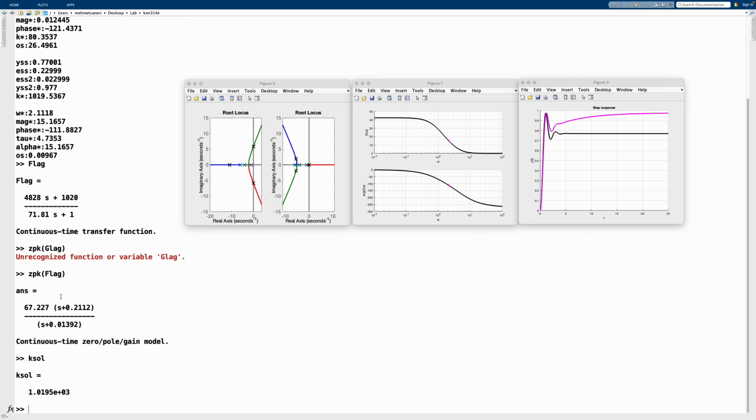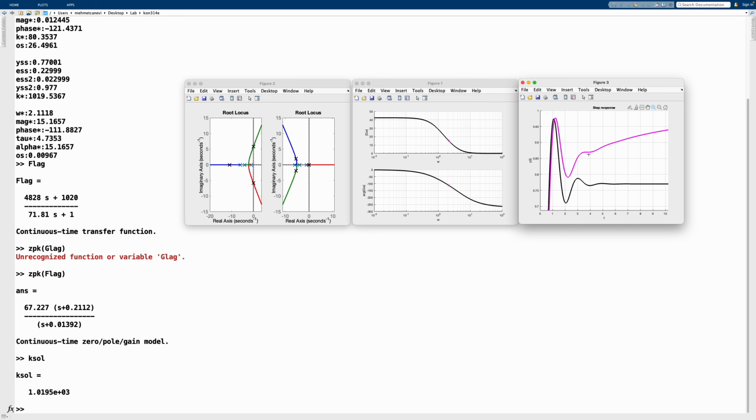and this is almost 1000, which is out of the stability region, but the lag controller compensated for that and increased the stability of the system so that we are kind of using this gain here. You can see it is not the best lag controller design that we would hope for, but it does its job. So yeah,